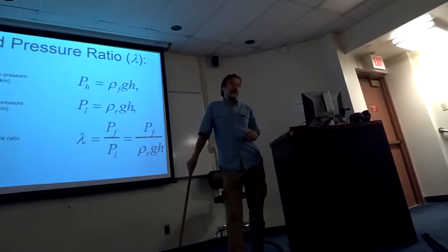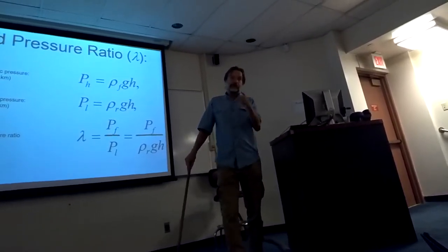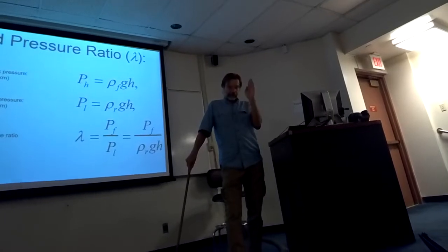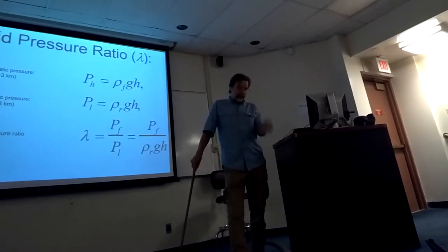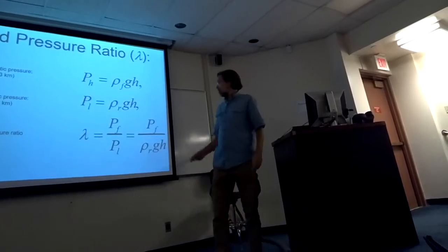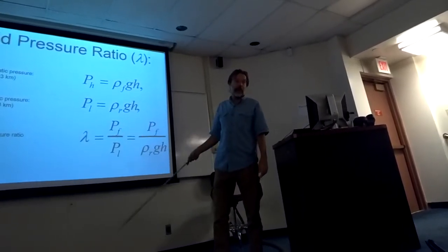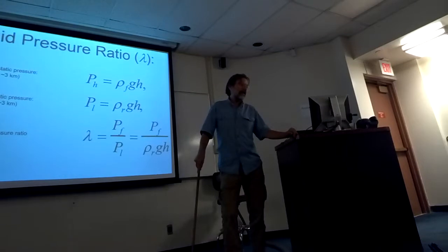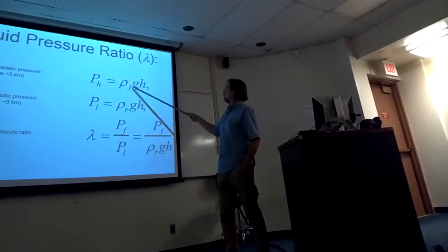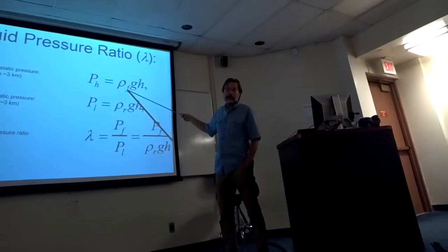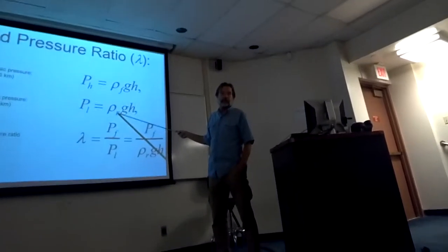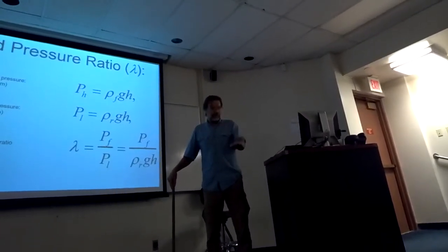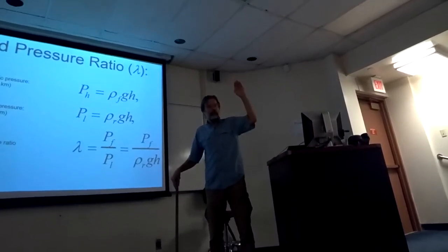What they found early on in the Gulf Coast, as BP found out, or was reminded of, because they knew it quite well, is that in Gulf Coast wells, when you hit certain horizons, fluid pressures are very close to 0.9, 0.95 in some of those rocks. The only way they figured out to get over it was to change the rho GH. Instead of putting water in the borehole, they used heavy mud. They increased the mud weight by adding barite, things like that. That increases the fluid pressure at the bottom of the hole, and the hole won't blow out.